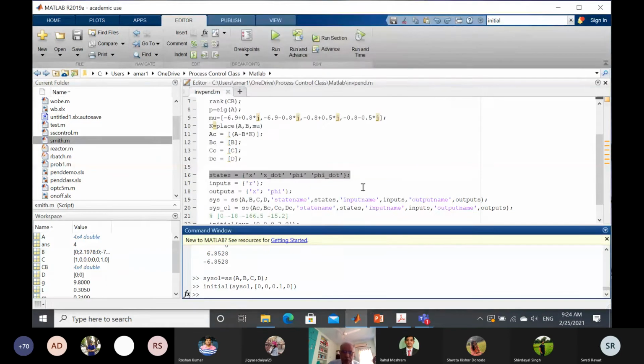So our objective, the first step, is that we design the feedback controller to stabilize the system. Okay, so to design that controller, we have to have a reference trajectory, because one of the poles over here is lying on the right hand plane. So the first thing is we pull back all the poles to the left hand plane.